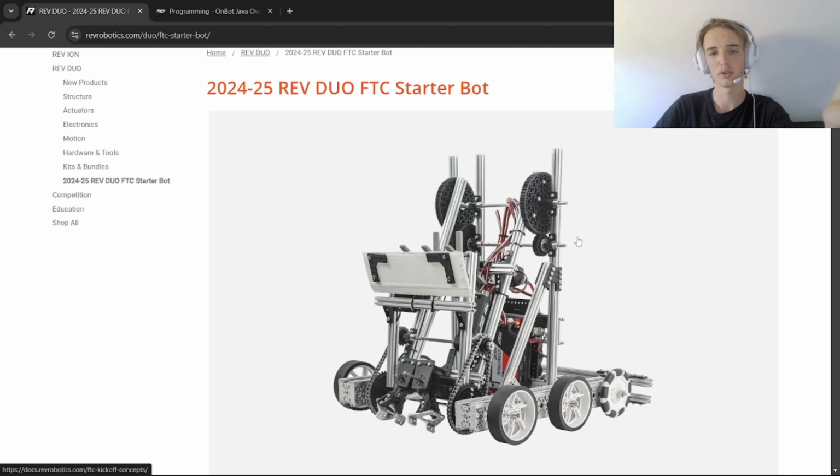So the actual code is very similar for the part that we did on Saturday, and I'm showing you here. So what exactly does need to change? The only thing we need to change is the position the arm goes to, because it's a different motor. It's got a different gear ratio. You can see here, small to big. Same thing for the Go Builder starter bot, except that it'll be a different gear ratio, so it'll go a different speed, go to a different position.